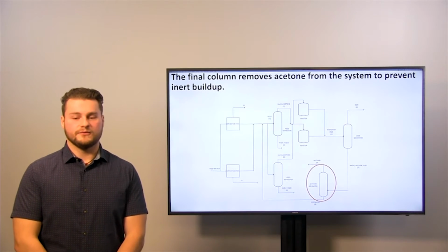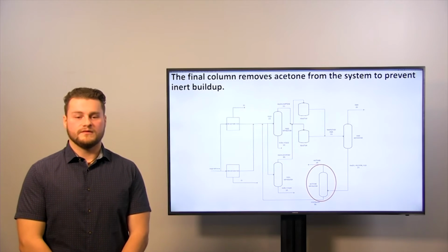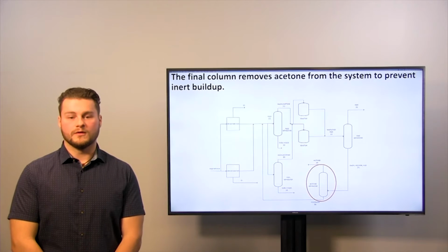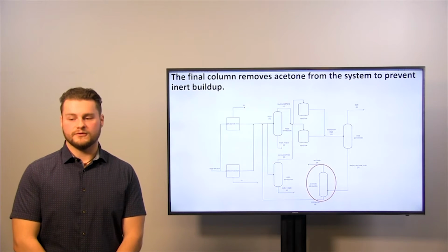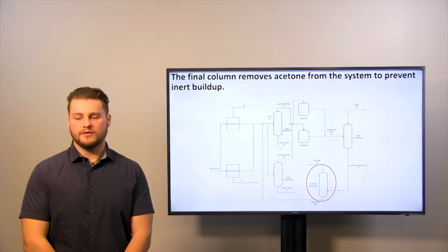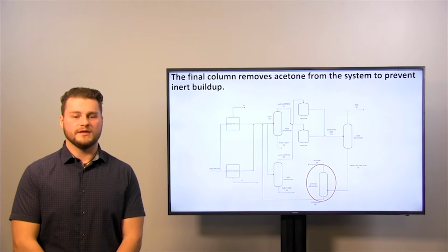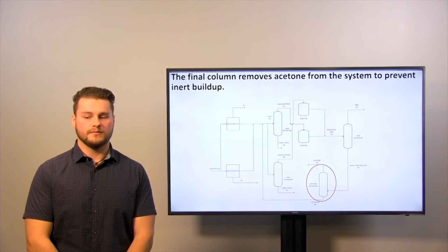Due to the dehydration reaction in the system, water is created, and this allows us to not have to pay for water or add water to the system. It creates a natural extractive distillation. The bottoms of the column, containing mainly methanol and water, are recycled and mixed with the impure methanol feed and sent to the first set of columns.